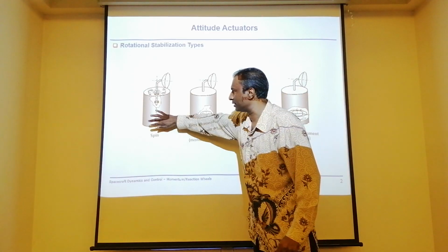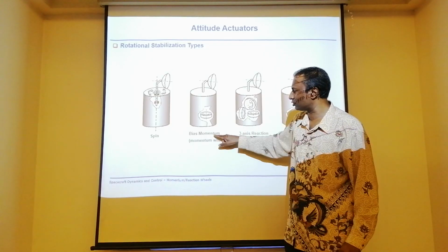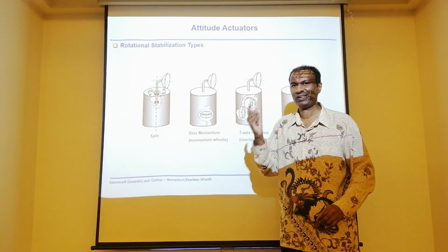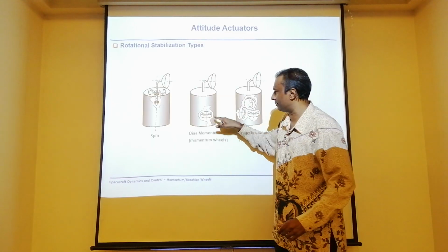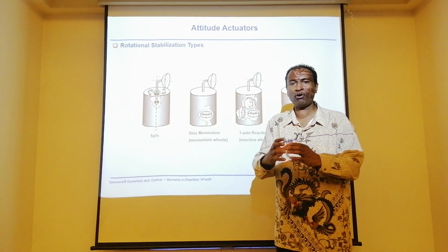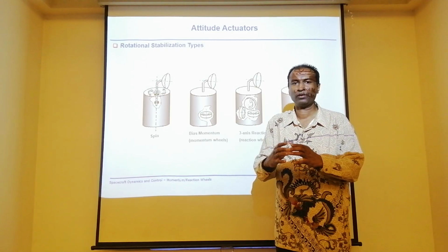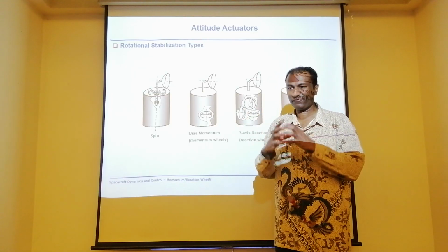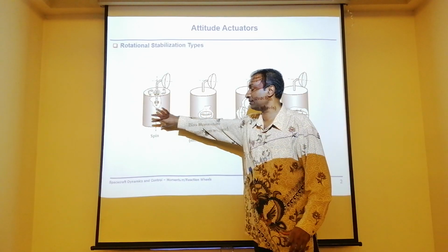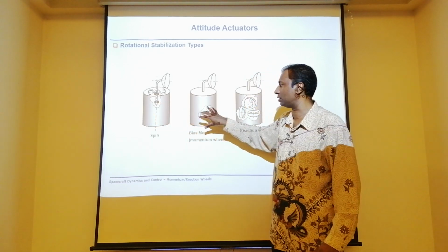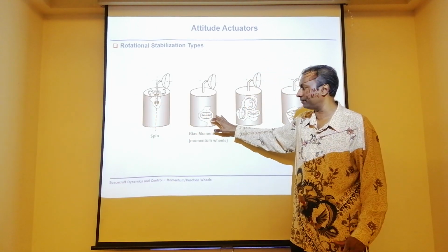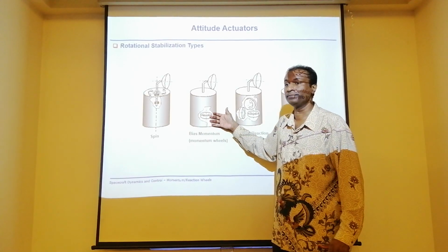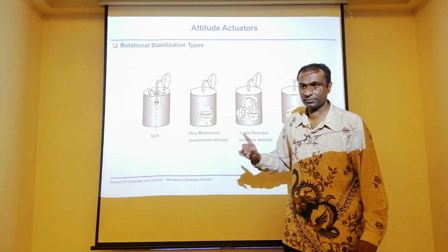Another way we do it, we stop spinning the body, install something called a wheel inside here, and command the wheel to spin very fast, to compensate for the small inertia that the wheel has. So it has to actually spin faster. When it spins faster, it can produce a similar or even larger amount of angular momentum that you need. So the passive stabilization can work. It can also produce the gyroscopic stiffness here. So this is a bias momentum type 2.